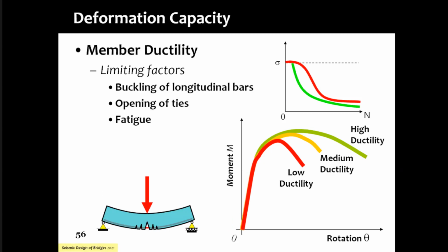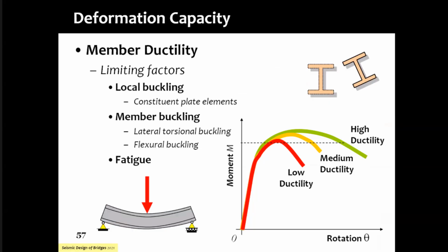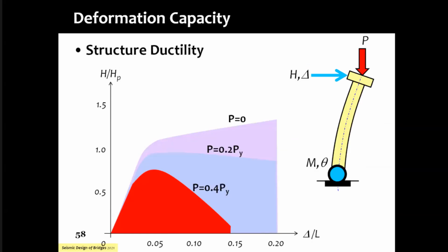One of the things is that if you have large diameter bars and poor grade of concrete or heavy corrosion, then you will notice that fatigue will become an issue for us, and we will lose ductility because the bond is going to get deteriorated quickly over time, right? And this is a matter that we want to ensure that fatigue is not an issue in the steel structures from the point of a bond slip, but it's an issue in terms of the welding part of it.